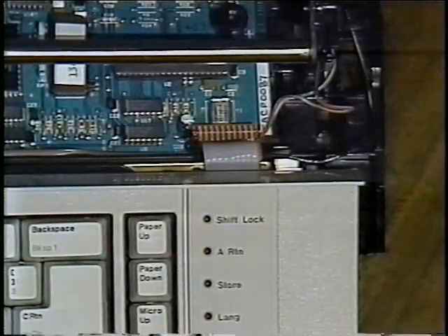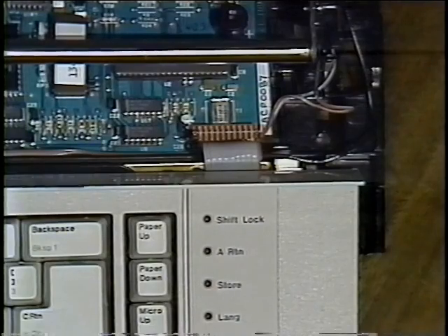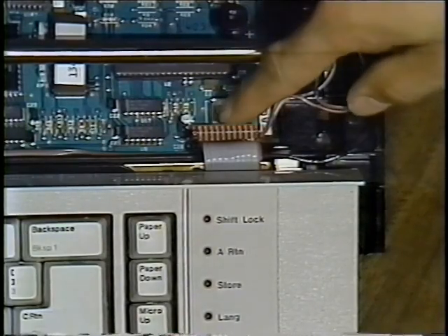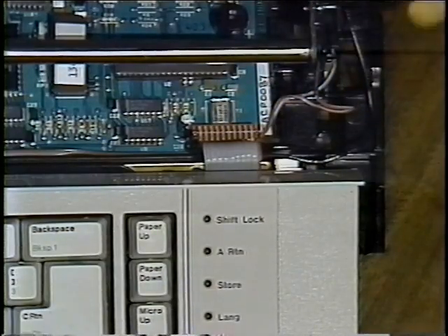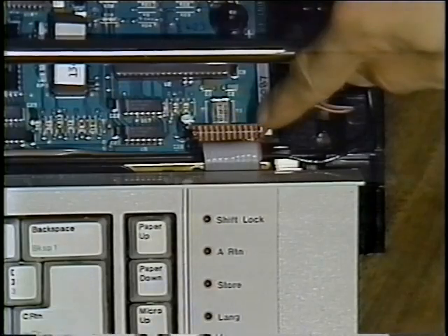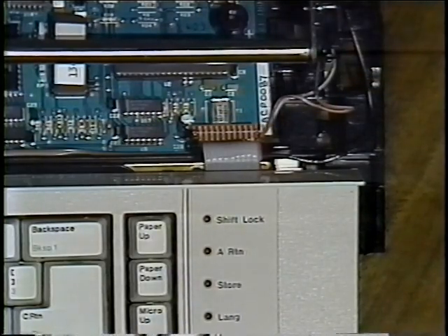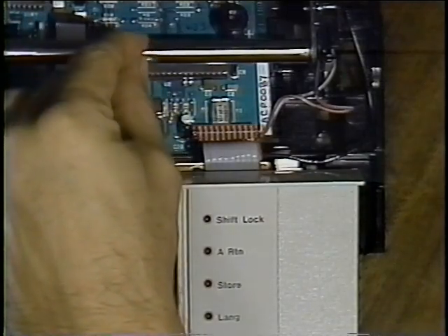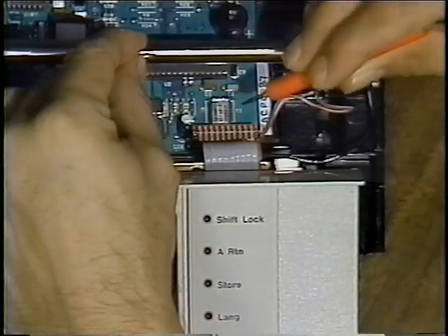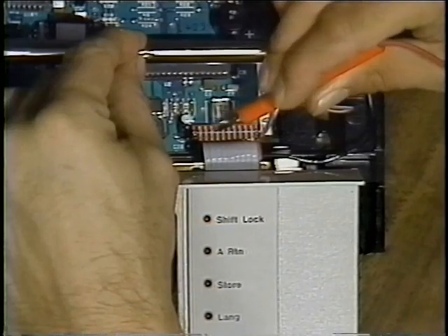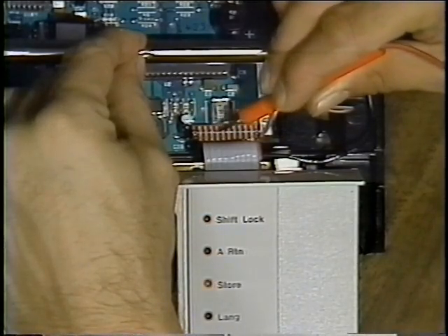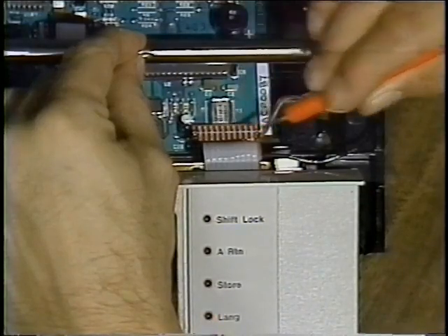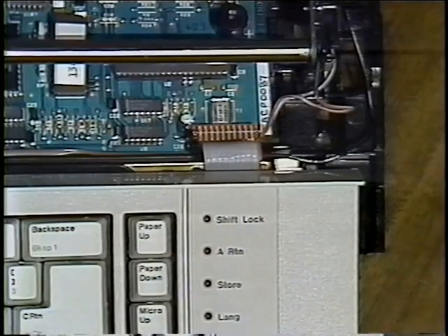Now let's see how to check the LEDs on the indicator panel. This is the indicator panel connector. Like the connectors on the printer board, this connector has a blank pin on each side. To see if the LEDs on the indicator panel are good, short each of the pins for the LEDs to ground one at a time. To do this, connect one end of a meter lead to ground and touch the other end to the pins. Do not apply ground to the plus 5 volt pin on the connector because this will blow a fuse in the power supply. This concludes the keyboard check section.